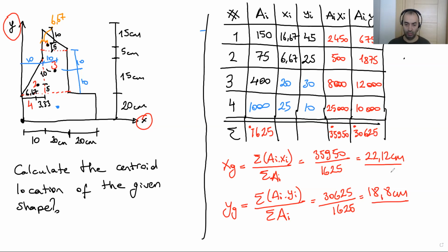Remember, we were using the Pappus-Guldinus method. I'm gonna write here actually. We don't need. The volume is, firstly we are gonna rotate this section around the x-axis. Angle times area times distance. That gives us the volume. Angle 90 degrees.